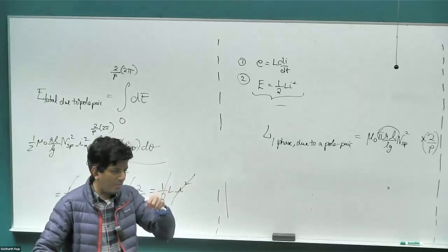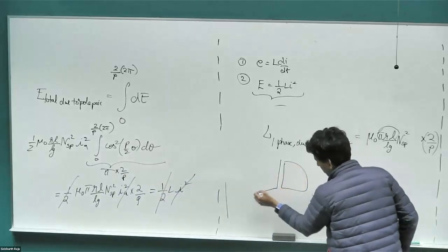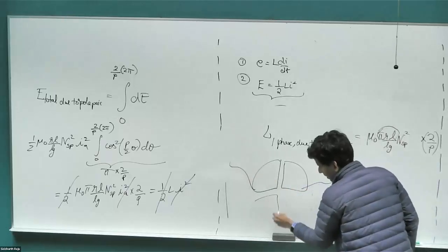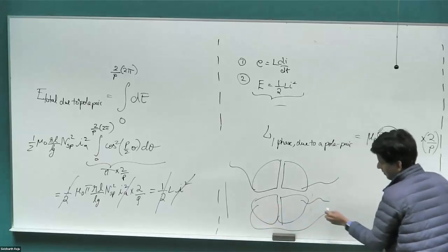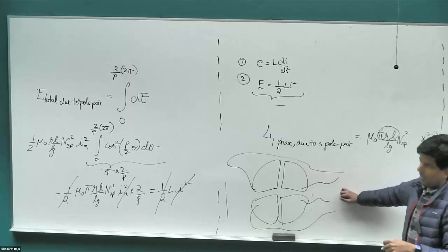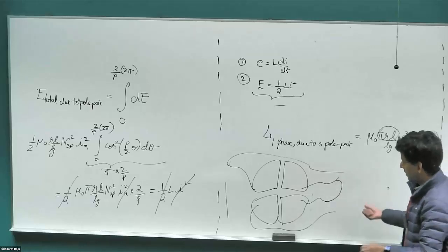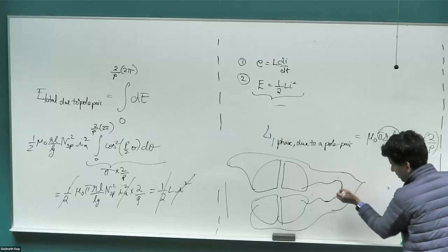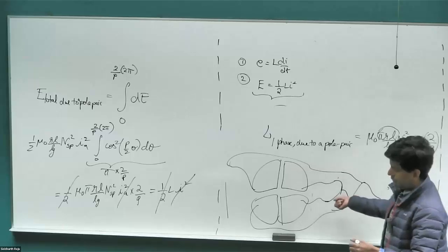Let's say I wind this set of coils and this set of coils. So I will have one winding and then one winding coming out. And then I can do the same for this one as well. One winding here and then one winding coming out. So I have two sets of separate coils now. I have multiple options. I can connect these in series, and then have these two windings come out, or I can put them in parallel and have two sets of windings come out. And this is the case when you have just 4 poles.